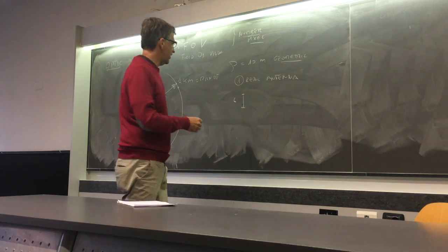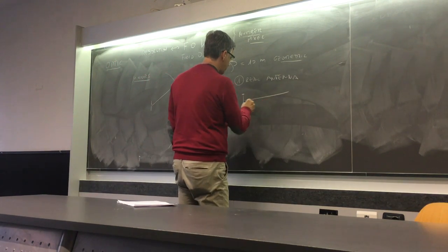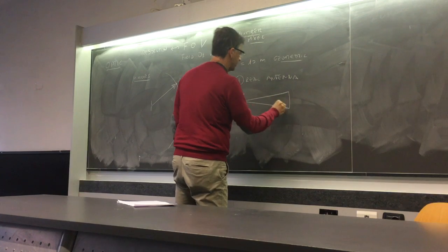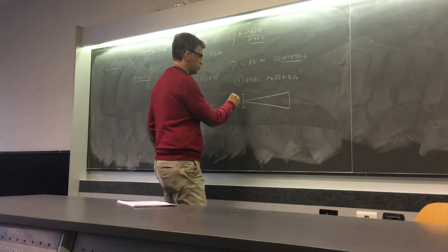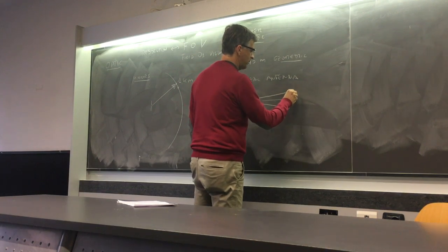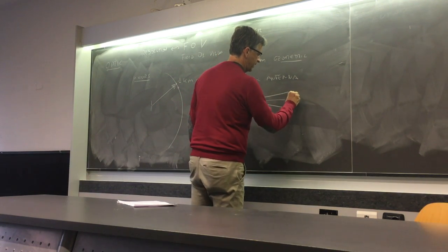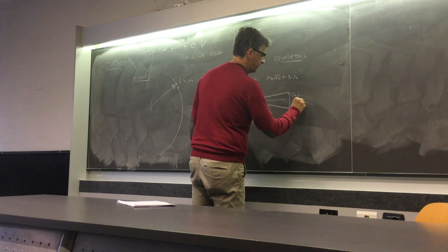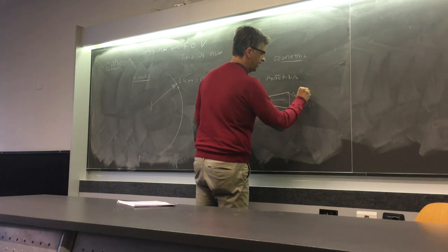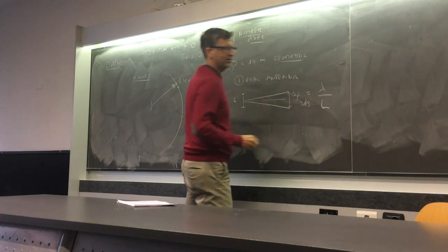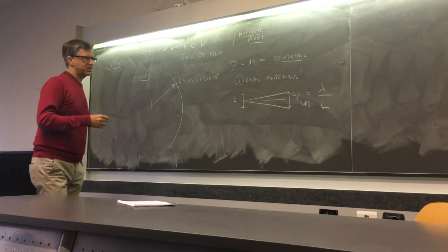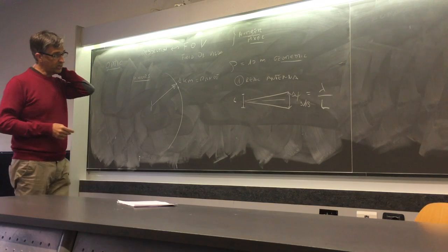Your antenna generates a beam that, different from a synthetic antenna, is always pointed orthogonal to the antenna. And you remember that the 3 dB beamwidth, delta theta, is approximately lambda divided by L. This approximation is not exactly this number, but we use this.